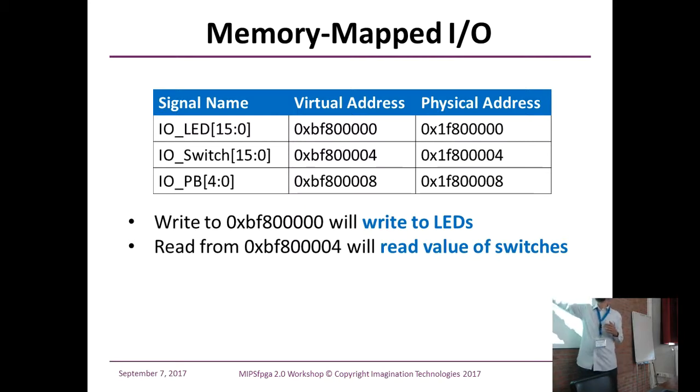Similarly for switches, this memory location is a register. We do a load word, and then we read what the switch is, is it high or low. So that's how we use software to read and write from peripherals. It's all memory mapped I/O. Similar for push buttons, it's this register. If we write to this address, it will write to the LEDs. If you read from this address, it will read the value. Once you start using it, it will get clearer over time. Memory mapped I/O is basically how all SoCs work and interact with hardware peripherals.